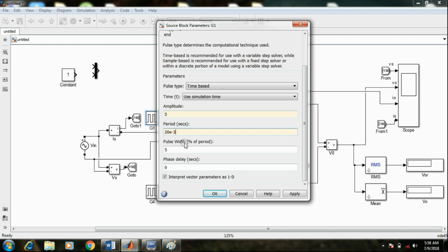Next, what is the pulse width? So for the thyristor to get triggered, we must give the pulse width so that the load current is just greater than the latching current. So let it be some 20% by the time latching current comes, let us say.